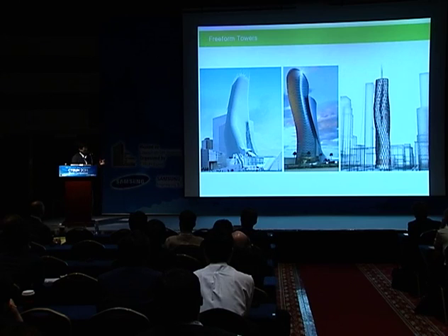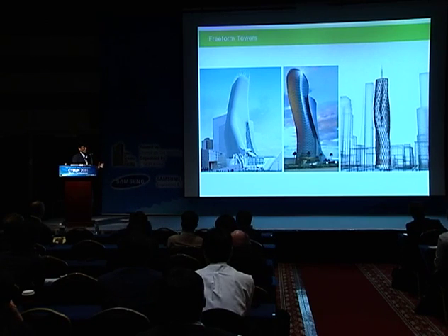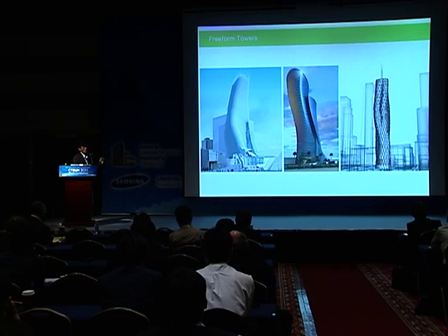My students' work began from the beginning with these diagrid structures, because, considering its characteristics, the diagrid is a pretty good system to better define freeform tall buildings. If you try to define any irregular freeform with a conventional orthogonal frame, for example with 4 points, it is very vulnerable to distortion in terms of defining it and carrying out the construction.